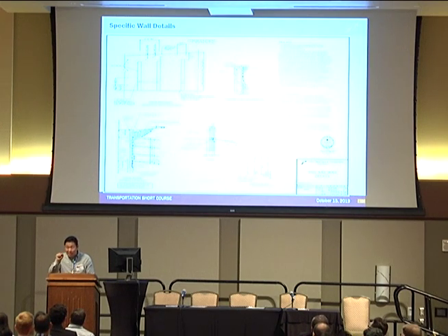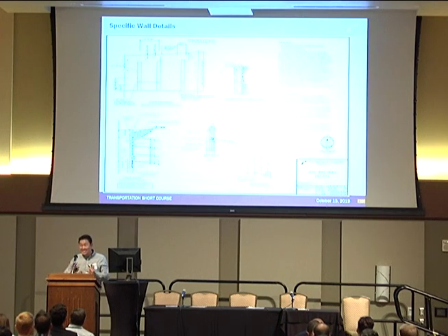You should have the soil nail and the structural face. One typical observation is that a contractor may not want to order a short shotcrete load, less than 7 or 9 yards, so they install the nail, wait until the next day, and bring the shotcrete another day. But it is not acceptable. You should punch, grout, and shoot the shotcrete on the same day.